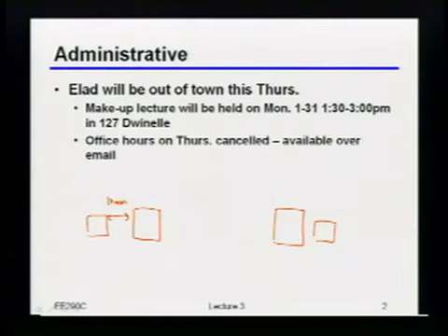Inductance. Yeah, so let's say there's somehow magically an ideal voltage source inside of that regulator. Well, guess what? There's some inductance to get onto my chip. And then inside of my chip, I've got this inverter. Well, what happens when I change the state of that inverter? What happens when I change it from, for example, outputting a 0 to outputting a 1? What happens to the current through the supply?